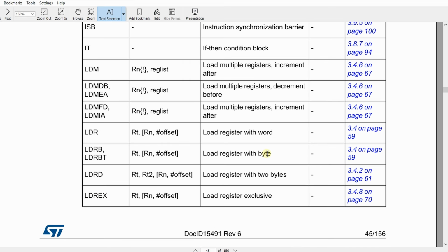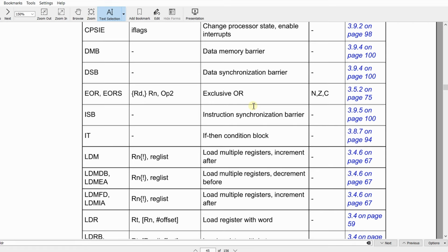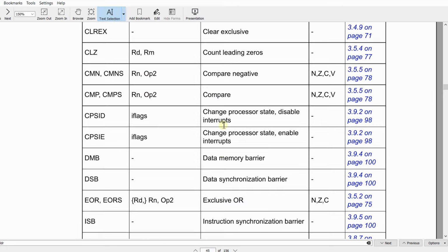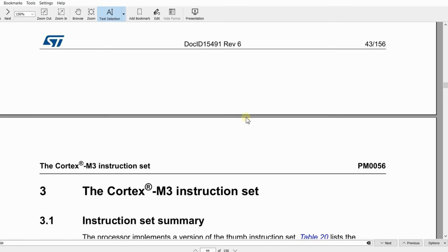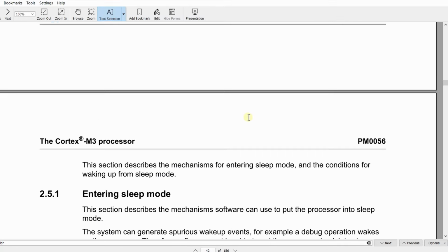Using the address in register R7 plus 20 bytes, we write the value from memory to R3. R7 holds the stack pointer, and we usually move parameters passed to the function and registers onto the stack to preserve the execution logic. That's all I wanted to show you about debugging.